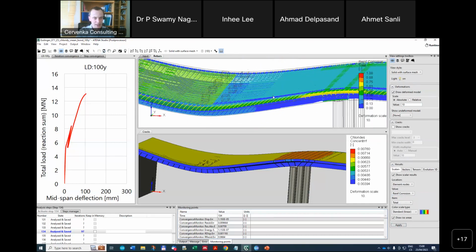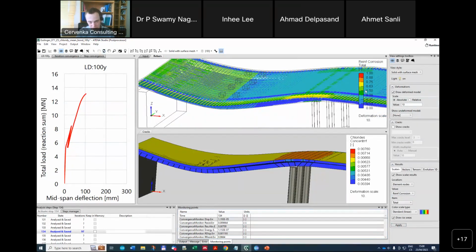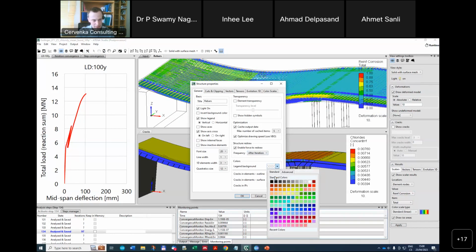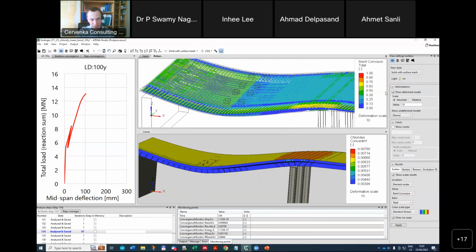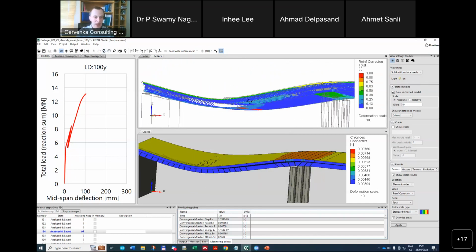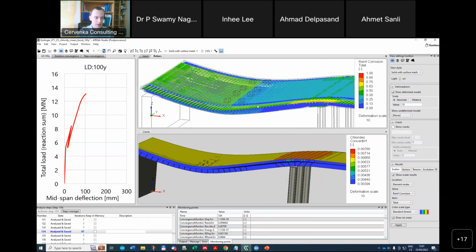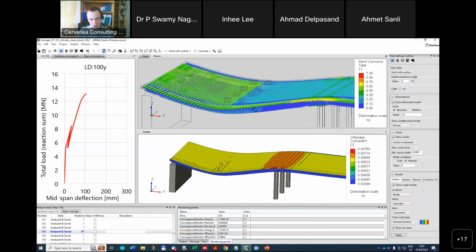However, mainly it's below. Let me see the scale clearly. Mainly we see the green color, which is about 50% of the reinforcement corrosion, meaning half of the cross section is gone at this moment due to the chloride attack.